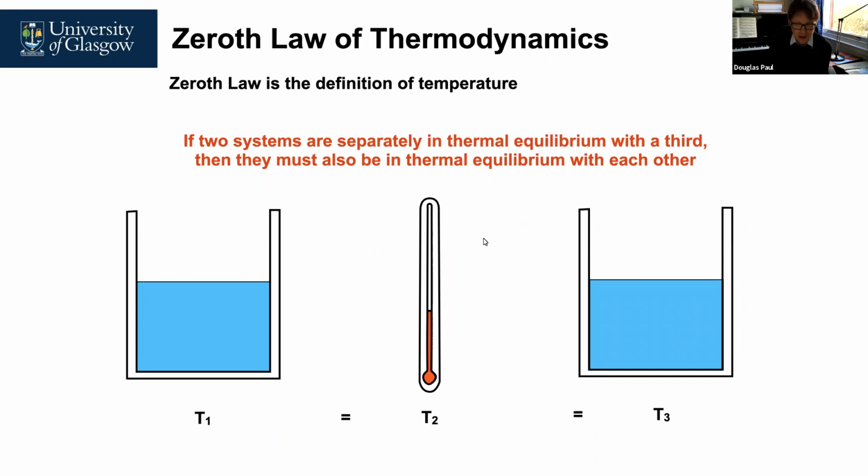We can get the temperature out. Now, actually, measuring a change in temperature is a relatively easy thing to do, with very high accuracy. Measuring the absolute temperature is a much more difficult thing to do. For most of what we're going to talk about today, having relative temperatures is good enough to get accurate efficiencies for power stations and thermal generation.